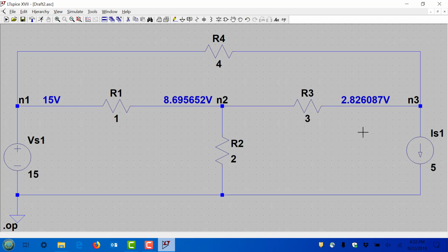So there's a drop of 5.48 volts as you go from left to right. So this side is higher than that side. So the current flows downhill. So we take 5.48 divided by 3. That tells me I should have 1.82 or 1.83, something like that. 1.83 amps going from left to right.